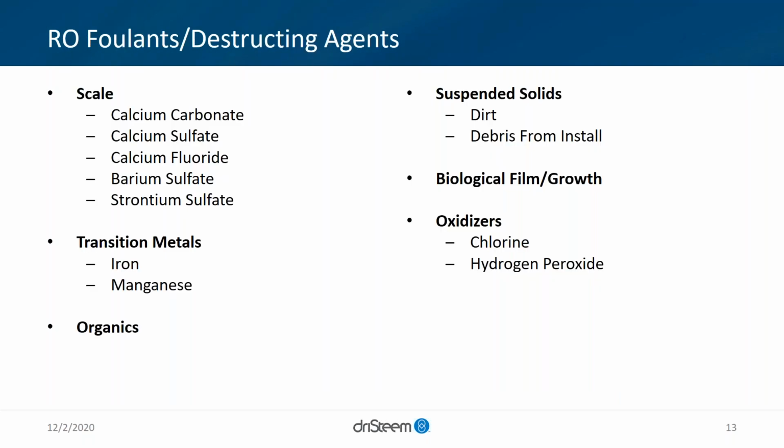Not going to dwell on this a lot, but there are things that we have to be cognizant of regarding ROs, just like the heat exchange surfaces. They can scale, they can foul. We really want to minimize that with pre-treatment and making sure we're operating our system accordingly.